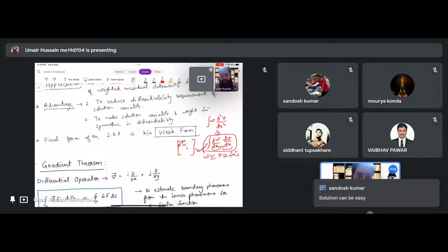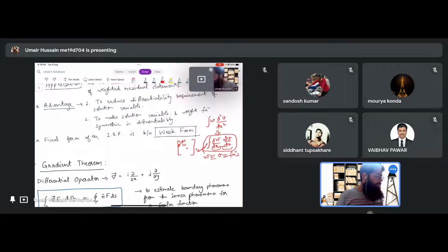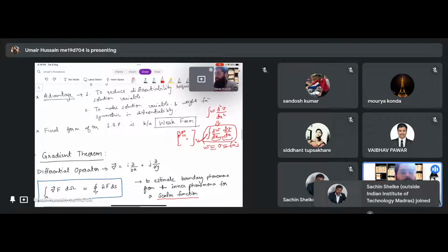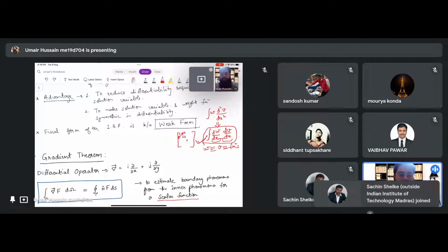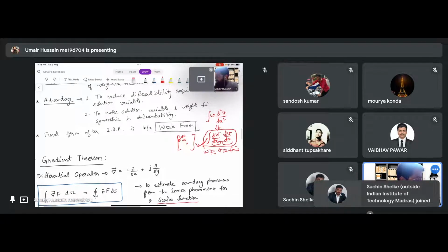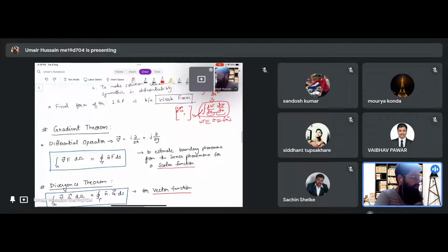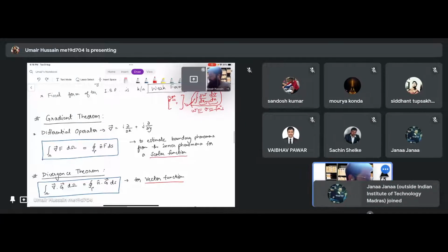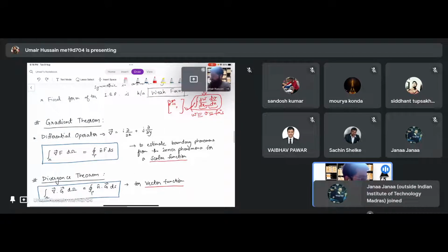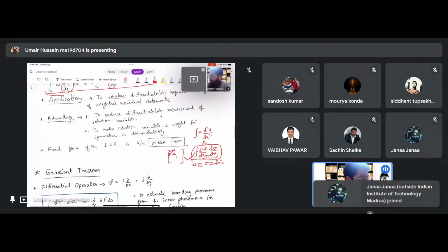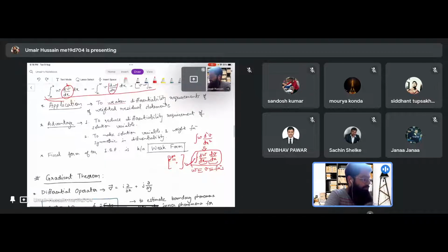Right, so yeah, exactly. Solving symmetric matrices is very easy. The algorithms built for symmetric matrices are simpler. In an unsymmetric matrix, it's a big pain. So yeah, this is the advantage of doing integration by parts. We reduce the differentiability requirement on some variable.